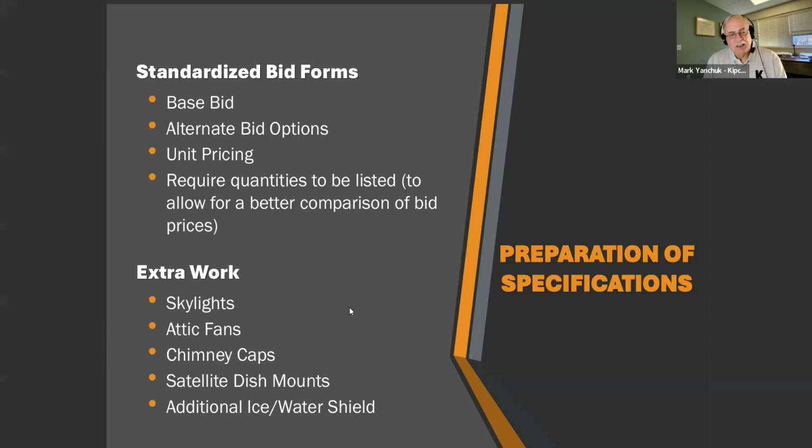But needless to say, the manufacturers of the shingles do not recommend having both an attic fan and, let's say, a passive system like a ridge vent on the same roof, because they could short circuit each other. For example, if the attic fan came on, it could be drawing air in from the ridge vent instead of from the soffit ventilation. So typically they are required to be removed during a roof project.